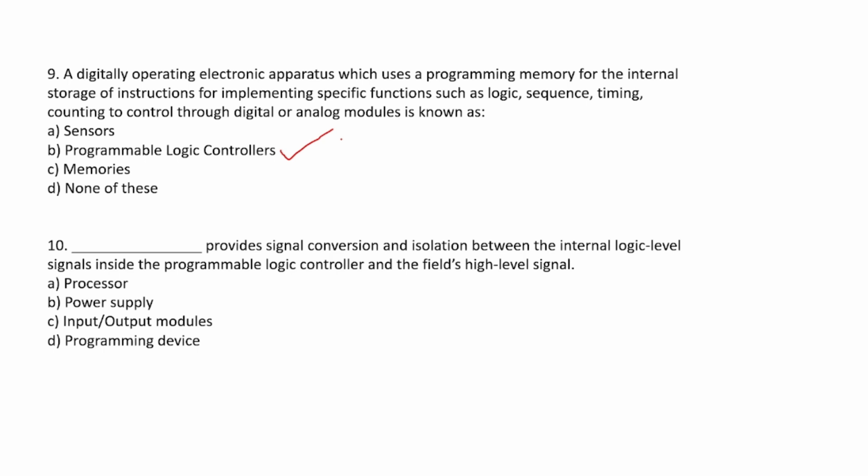So input modules convert signals from discrete or analog input devices to logic levels which the PLC processor can accept, and output modules convert signals from the processor to levels capable of driving the connected discrete or analog output devices. That is how the input output module works.